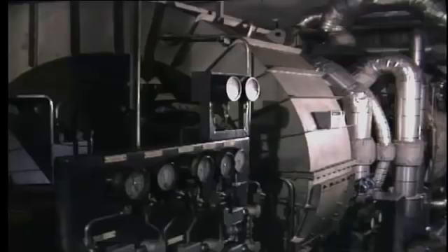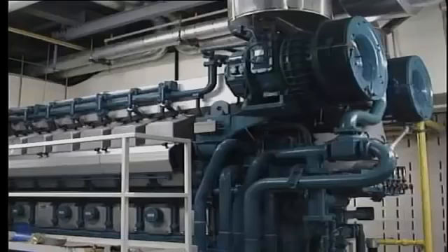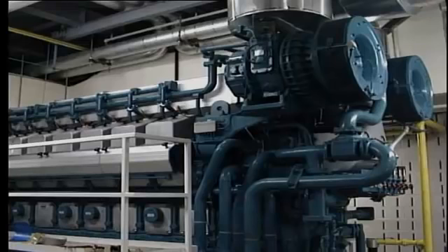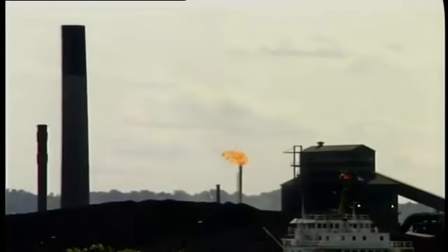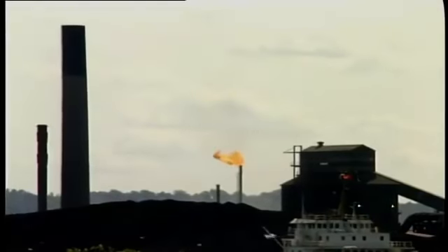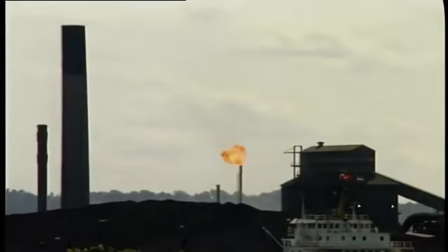Up to now, we've been considering that our boiler obtains heat by the combustion of fuel. But in many applications, particularly where cogeneration is involved, the heat is provided by high-temperature waste gas. This may come from several possible sources, such as the exhaust from a gas turbine, the exhaust from a diesel engine, or waste gas, commonly known as off-gas, from an industrial process.